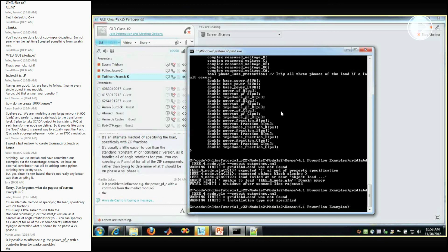Something you can do to prevent it as well, if that really was a problem, is you can go in and tighten up the convergence criteria, and that may help bump you out of that local minimum as well. But as Jason mentioned, we pretty much haven't ever really had a problem with that. It always converges to the global one.